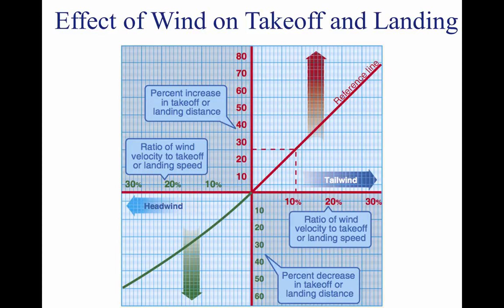Assuming that the acceleration is essentially unaffected, the takeoff distance varies with the square of the takeoff velocity. The effect of pressure altitude and ambient temperature is to define the density altitude and its effect on takeoff performance. While subsequent corrections are appropriate for the effect of temperature on certain items of power plant performance, density altitude defines specific effects on takeoff performance.